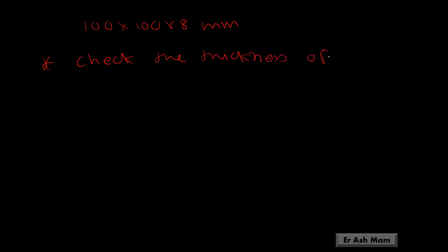Next is check the thickness of angle. Because in the start we have assumed that the angle section is 100 into 100 into 8 mm. This was an assumption. Let's check the thickness of angle with the help of clause 8.4.